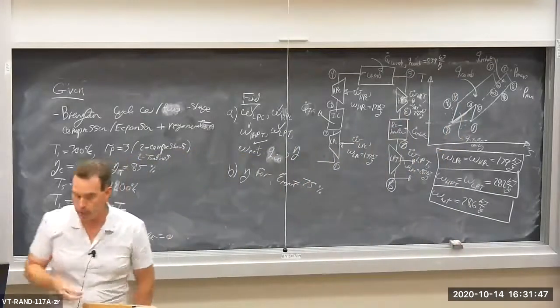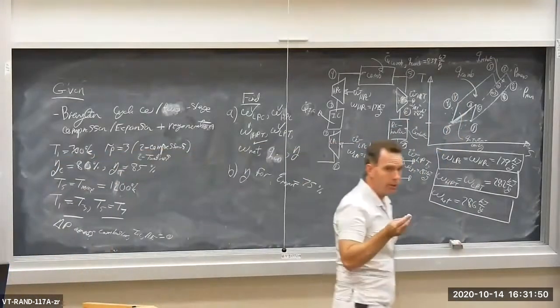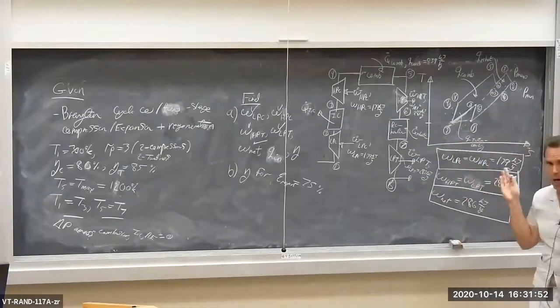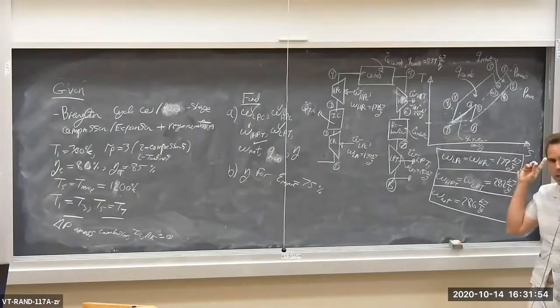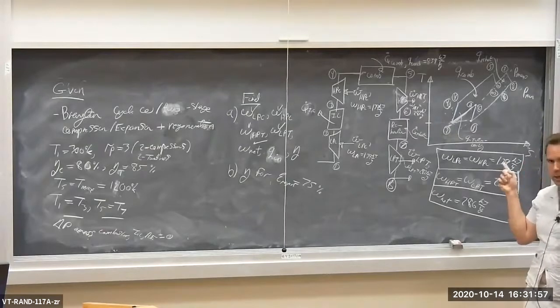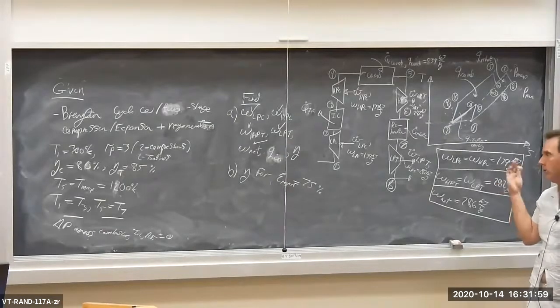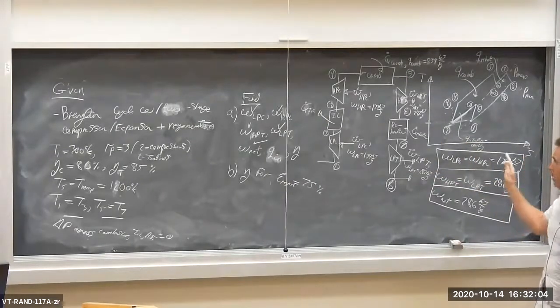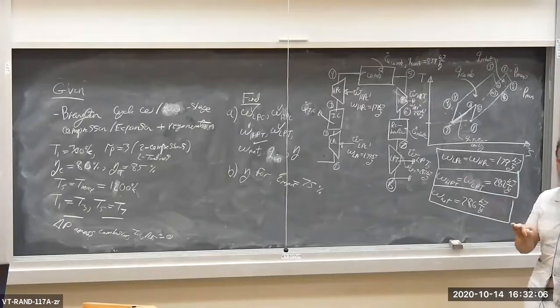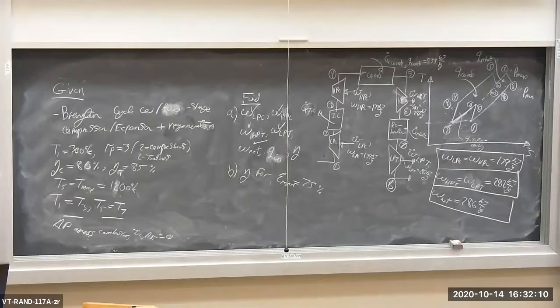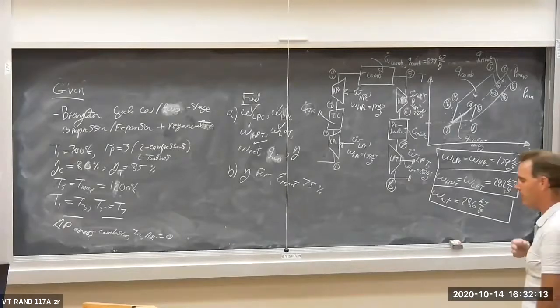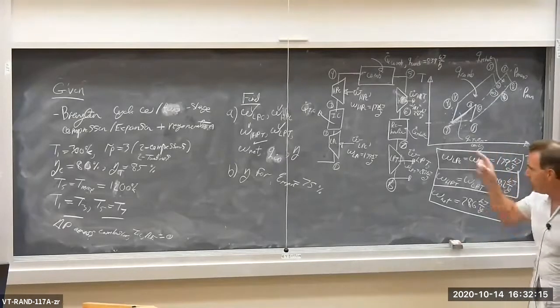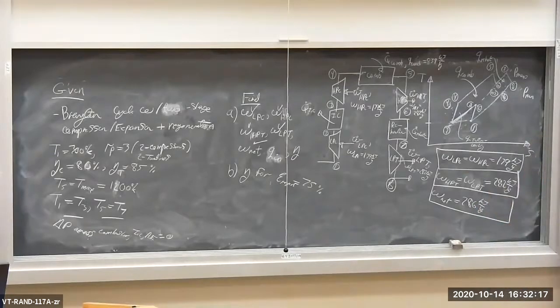All right. Listen, I hope this is driving home the point that you need to get comfortable drawing the TS diagram for the cycle or the process or the device, drawing the device, indicating the various states. If you don't do this, you're screwed, okay? So for those of you doing your problems without doing your TS diagrams or PV diagrams or some kind of diagram, and you're not drawing the device, you are utterly lost at this point.